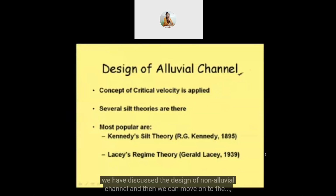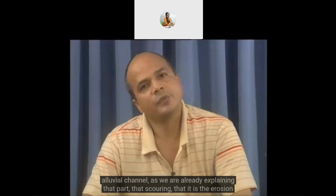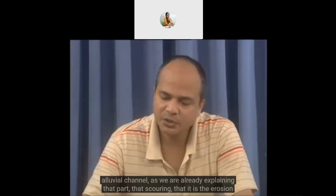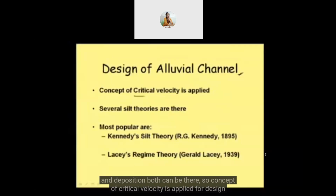Then we have discussed the design of non-alluvial channel, and then we can move on to the design of alluvial channel. Well, now for analyzing or for designing alluvial channel, as we are already explaining that part, erosion and deposition both can be there. So the concept of critical velocity is applied for design of alluvial channel.